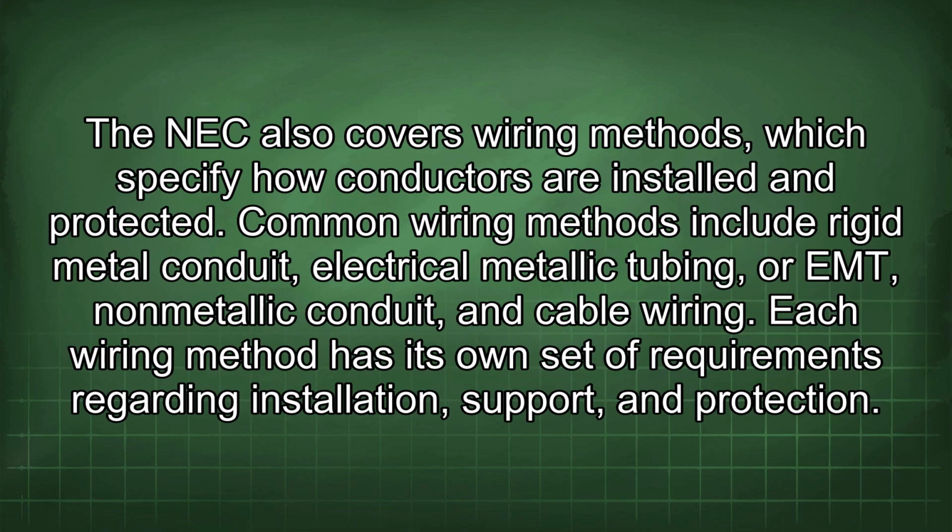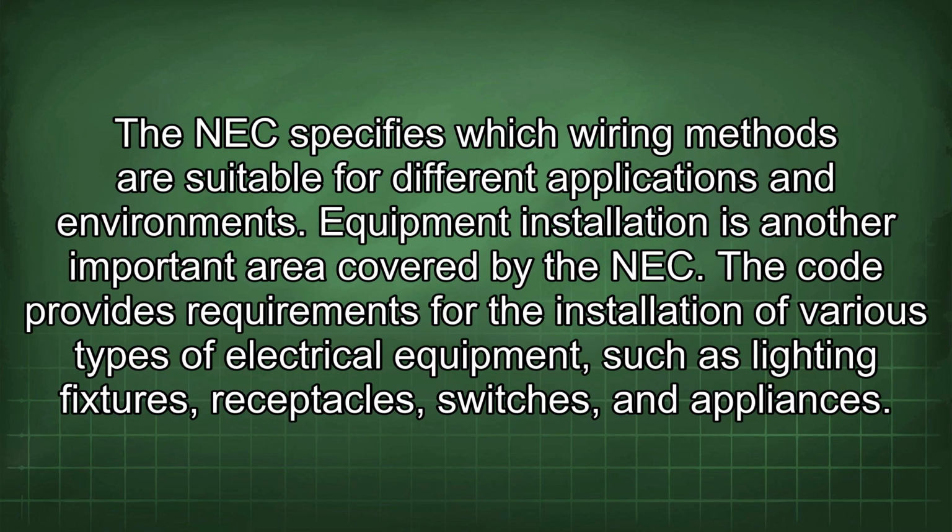The NEC also covers wiring methods, which specify how conductors are installed and protected. Common wiring methods include rigid metal conduit, electrical metallic tubing, or EMT, non-metallic conduit, and cable wiring. Each wiring method has its own set of requirements regarding installation, support, and protection. The NEC specifies which wiring methods are suitable for different applications and environments.